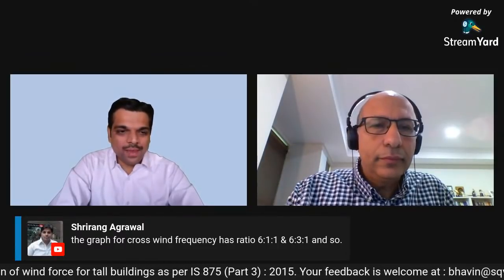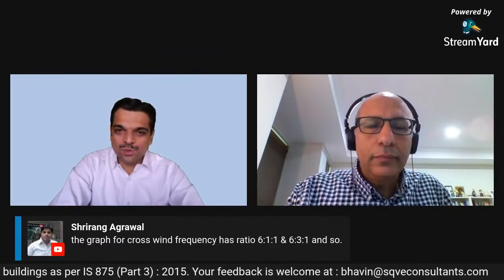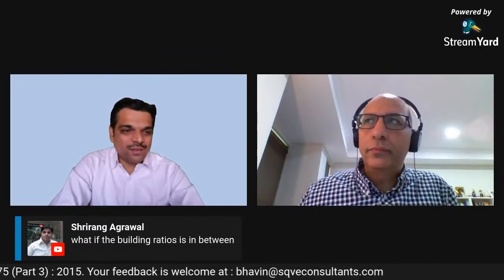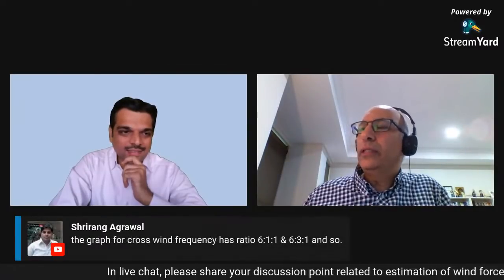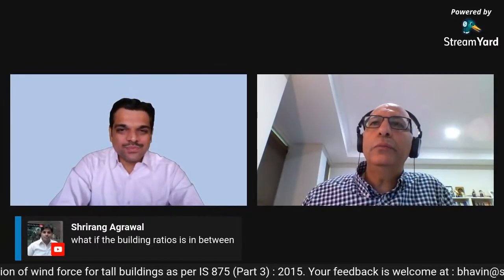Okay, there is one more question. In the graph for crosswind frequency, there are ratios of 6:1:1 and 6:3:1 and so on. So what if the building ratio is in between these figures? There is a 6:1:2, and a 6:2:1, and a 6:1:1, and so on. So what happens? You can interpolate. You are permitted to interpolate.